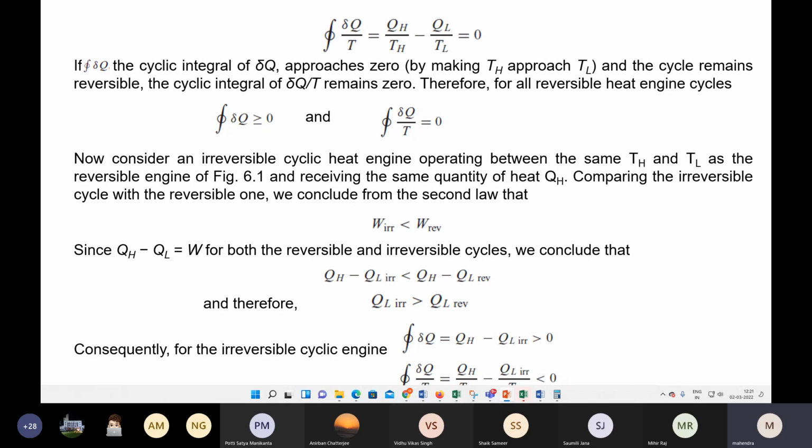The engine, we are considering it as a reversible engine. Okay. Then eta, meaning efficiency, equals 1 minus QL by QH. Yes, in our previous class itself, we have defined it. The same eta equals 1 minus TL by TH, if it is a reversible engine and it is a Carnot engine. Okay, so then 1 minus QL by QH equals 1 minus TL by TH.